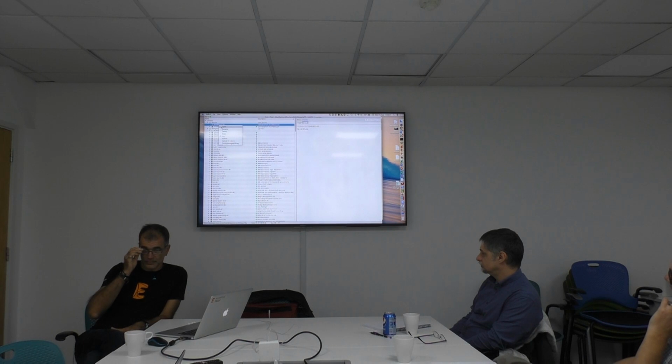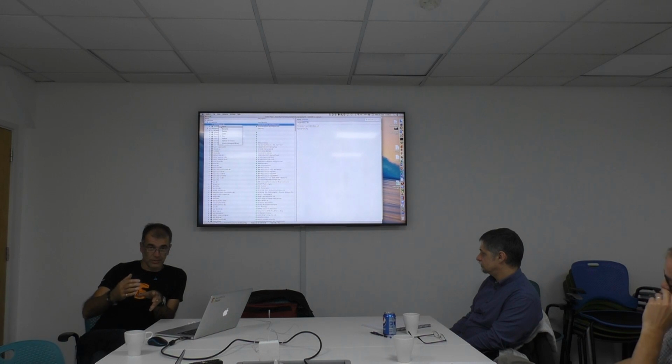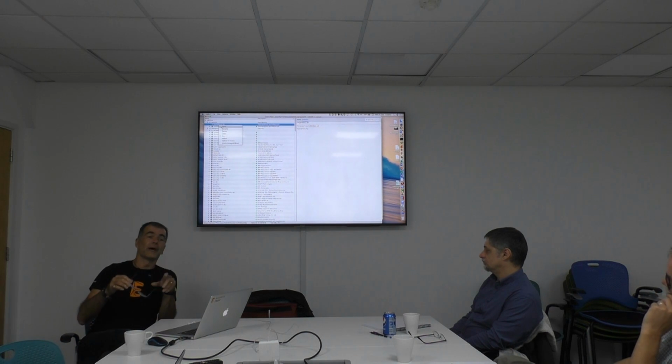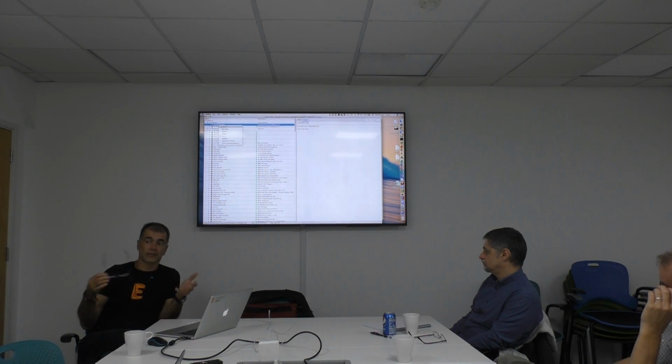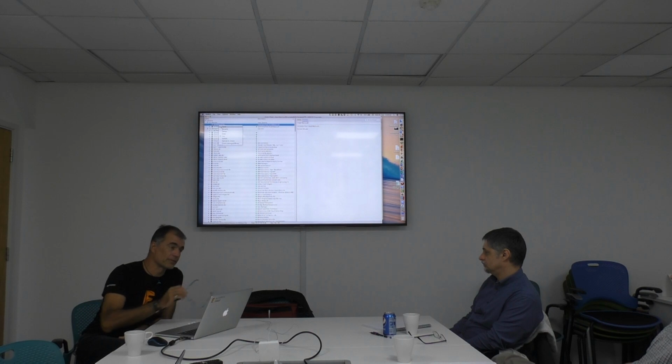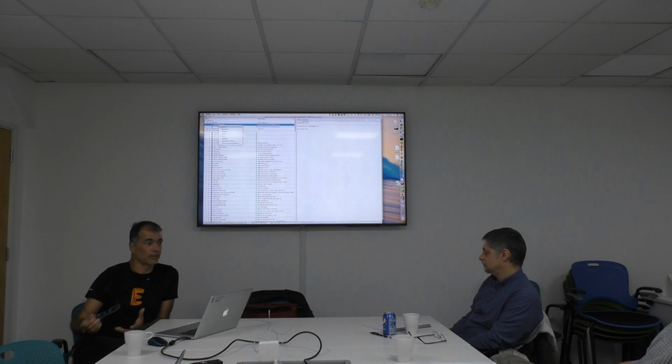Because you get a package of libraries when you install Eagle, and of course from time to time we update them. At the moment you get updates with new 3D models linked into the libraries. If we allowed the customer to edit the libraries, then you get a mess. So if somebody wants to edit one of the managed libraries, he could copy it, so it's an unmanaged normal library, and then he can do what he wants. He could again make it his own managed library. That's also possible.